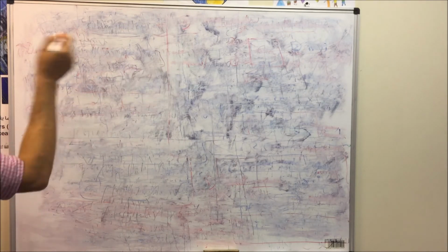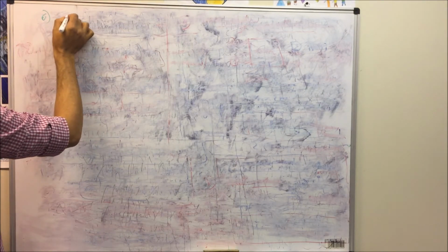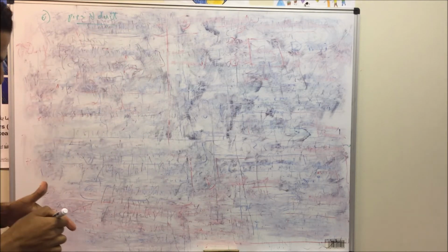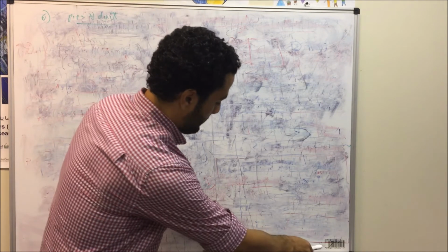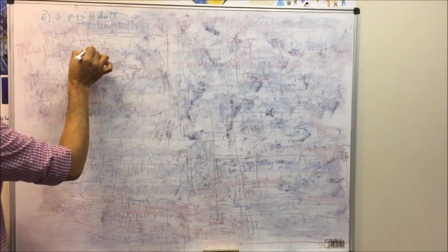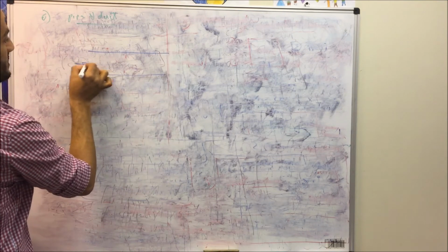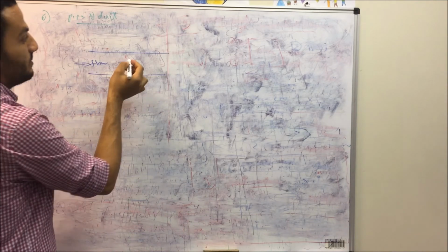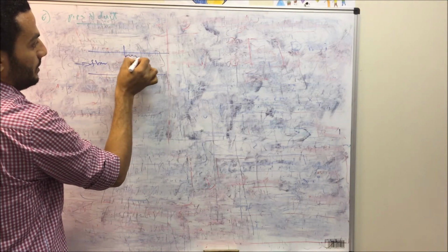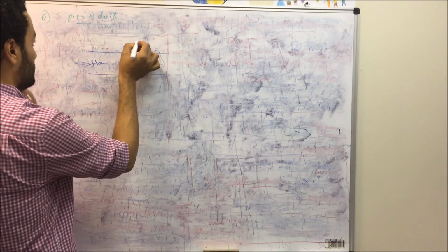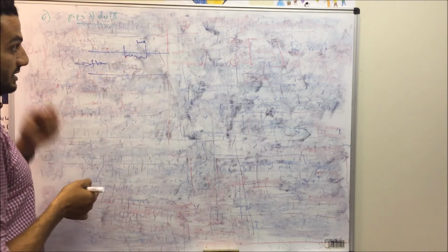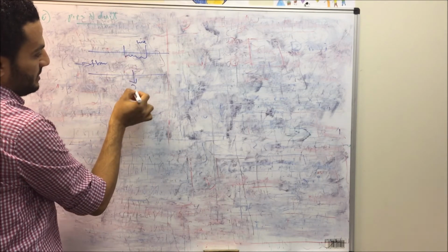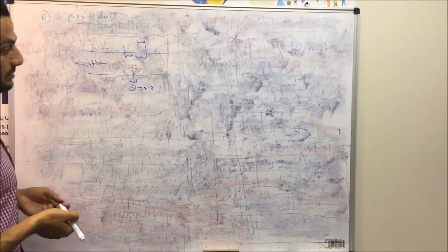The last steady flow device is the general flow in pipe and duct. Okay. So when we have flow in a duct, like any pipeline system, in some cases we need to keep it warm, so we can heat it using an electrical heater. So we may have electrical heat input. If it is insulated, we don't have heat transfer, but in some cases the system may allow for heat transfer.